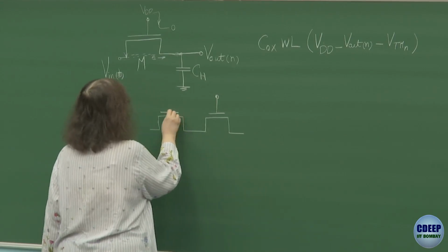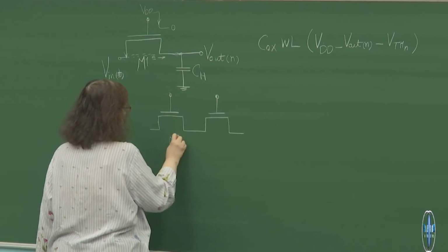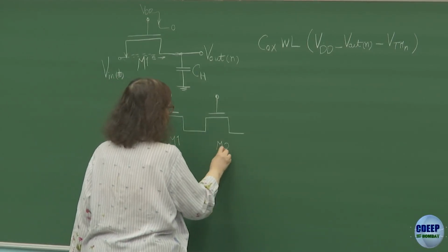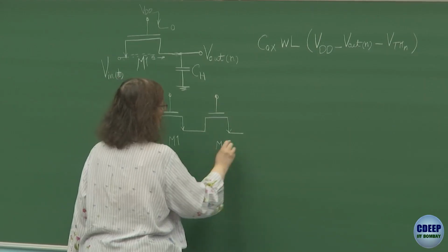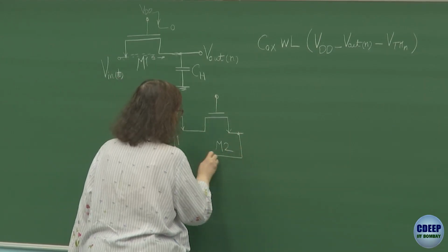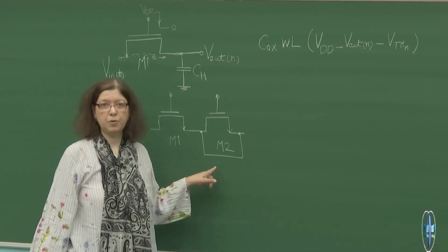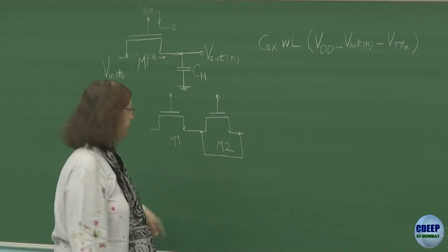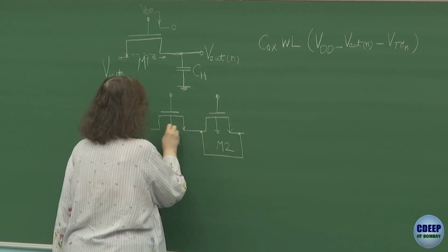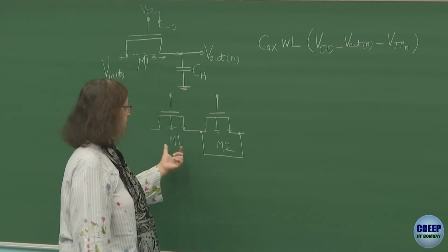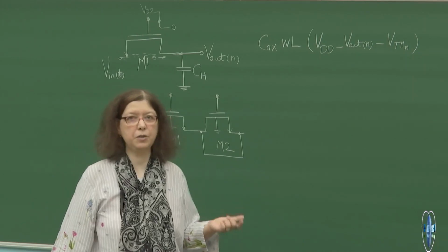So imagine that we have transistor M1 as a main switch and transistor M2 as a dummy switch. Since the dummy switch is only a capacitor, we connect the drain and source terminals together, and the bulk could still be connected to the ground. And as we have considered before, for now we ignore the effect of body effect on the variation of threshold voltage.